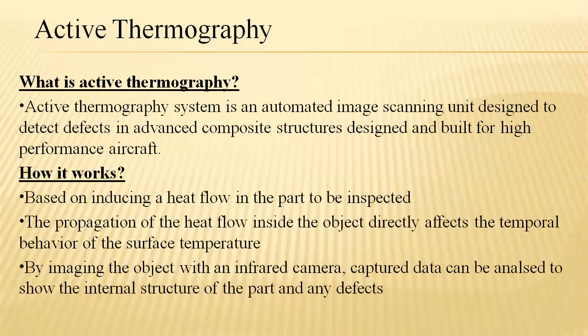So whatever heat is propagating in the form of IR rays into the object is used to examine the composite structure of the object. Whether it has the bonding nature or not, whether it holds perfect mechanical properties, or its solidification during the casting process. And if there are any flaws, air bubbles or voids existing in the casting process, all this will be clearly verified.